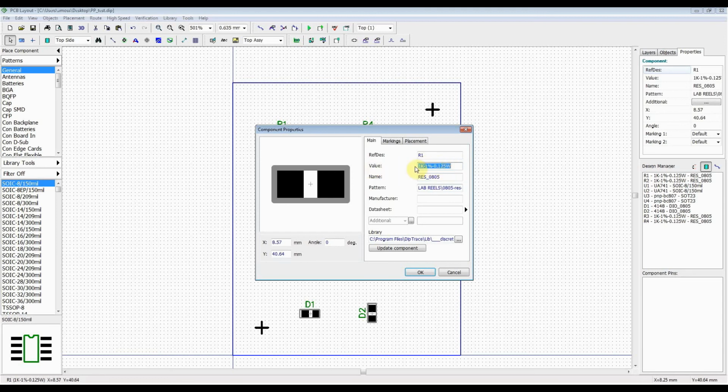That value is critical. That has to match your component part in the pick and place machine. So in your pick and place machine, if you've only denoted a 1K resistor as being 1K, then it will be 1K in your pick and place machine. If it was say 1K 1%, then it'll be 1K 1%, and so on. It is case sensitive, it is white space sensitive, it is little dashes and wibbly wobbly bits sensitive.